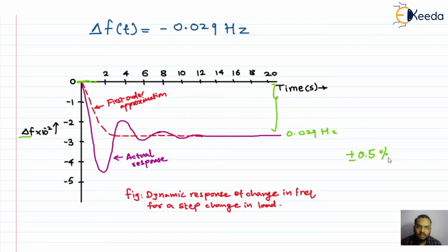You may experience a number of problems in the power system. The synchronism problem you may experience. Again, as I said, the whole system may collapse, and there may be a complete blackout. Again, see, if we keep the frequency constant, we can use synchronous clocks at various locations where we have the electrical network.